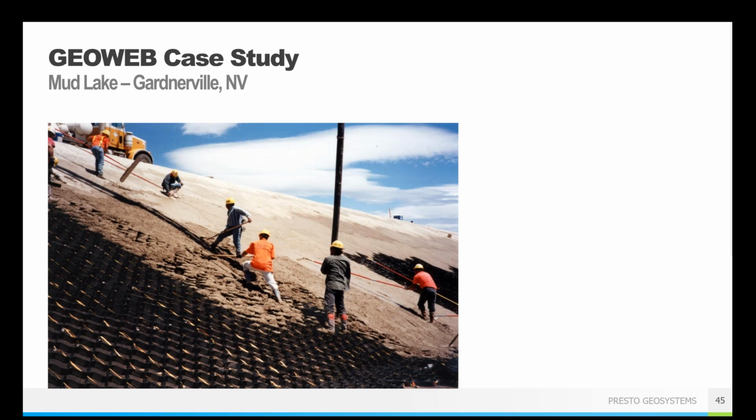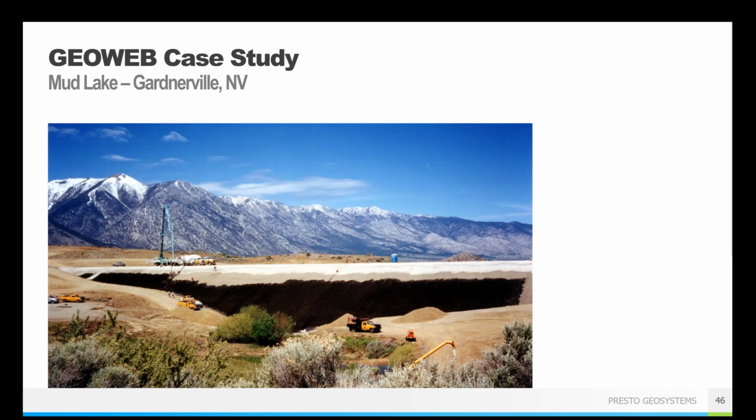And then you do typically want to pump that from the top to the toe. That is just an ease of installation thing, to help keep pushing the concrete down so that it reaches in and fills every cell. In this case, it was only a 2 horizontal to 1 slope, so that's why the guys were on that slope face. They didn't seem to have any harnesses. Leave that up to your own OSHA regulations as to whether or not that's acceptable to you, but you can see that going in here.